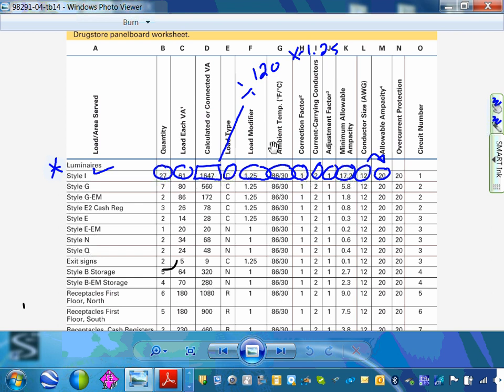One more time, gentlemen. You take the 17.2 to 310.15(B)(16) under the 60-degree column. What size wire do you have for 17.2 amps? Number 12, right? Did you find number 12? Verify it. Well, when I did the math, it came out to 30.88 amps. I got 17.15. You did the math wrong then. Yeah, it's 1647 divided by 120. Then multiply that answer, pull it down and start again, probably. Yeah, then you multiply by 1.25.